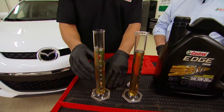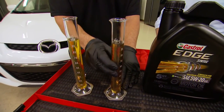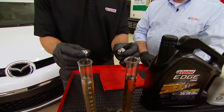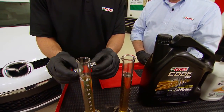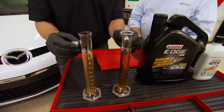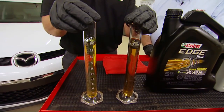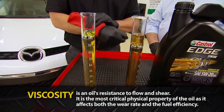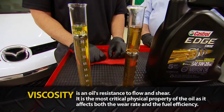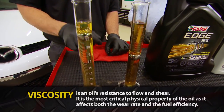Now it's almost like the flow of it, and we got a cool demonstration where we can show you the thickness of the oil. Right here we have 80 weight oil, and over here we have 5W30 oil. And what I'm going to do is take these little balls and drop them in the beaker. In the 80 weight oil, the ball is going to travel really, really slow. And the thinner oil, it should go a lot faster. So let's drop them in and see what happens. Now you can see the lightweight oil, it's flowing right through there, and the thicker oil, it's having a hard time getting through there.